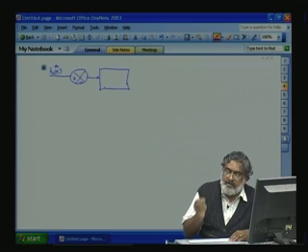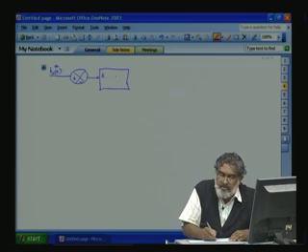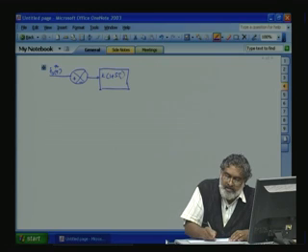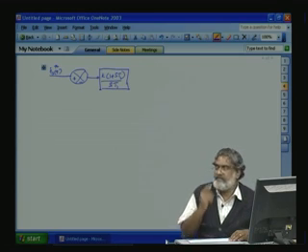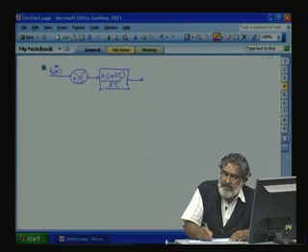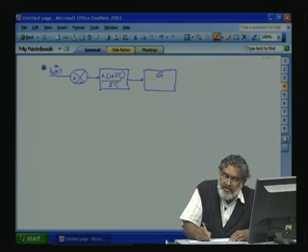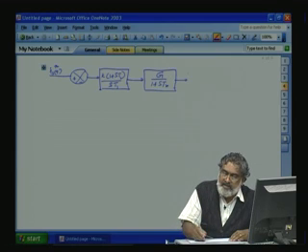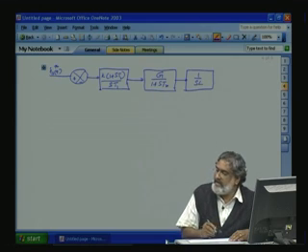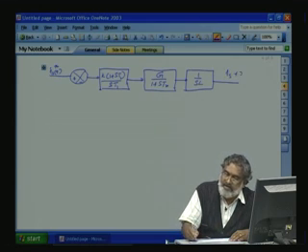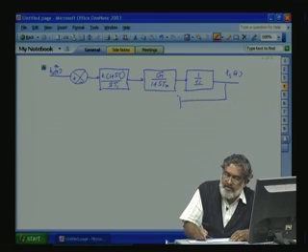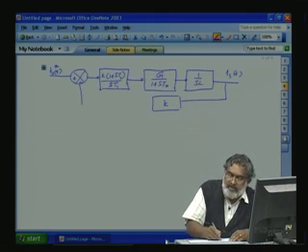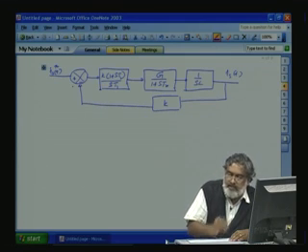The PI controller transfer function is represented as K into (1 plus ST1) by ST1, into G by (1 plus S TR), this is our converter, then 1 by SL, and this gives our actual current, which we sense and bring to the controller level.